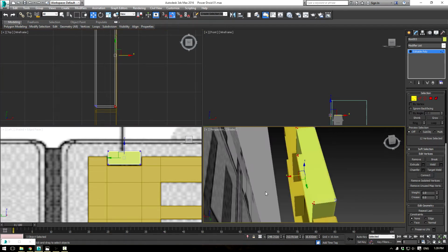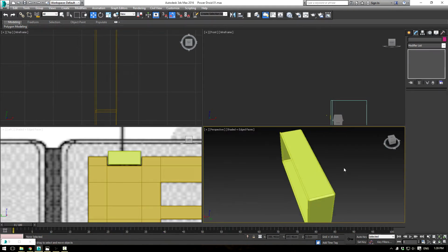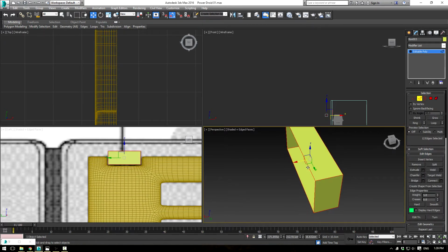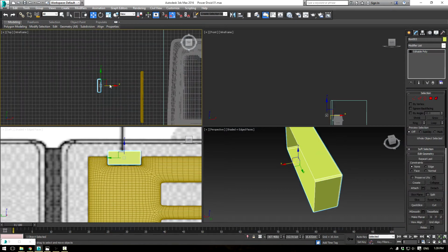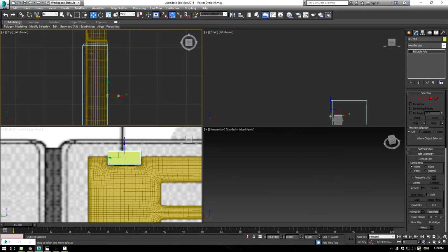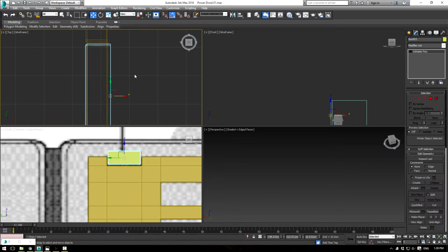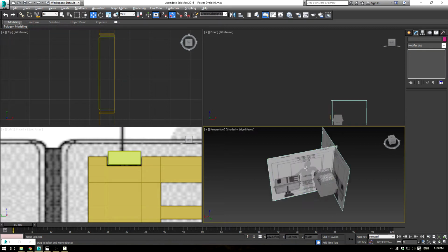And actually, we did that chamfer a bit wrong on this one. You'll see we have multiple lines there, so let's undo that. Alright, there we go. So grab all your edges with the exception of the back edges there. Then chamfer it at 0.5. Now we can bring it back and align it. So it's just little things like that that you need to watch out for, just to make sure that everything works. Alright. I just deleted the turbo smooth over there just because we don't need it for now. Alright. There we go.